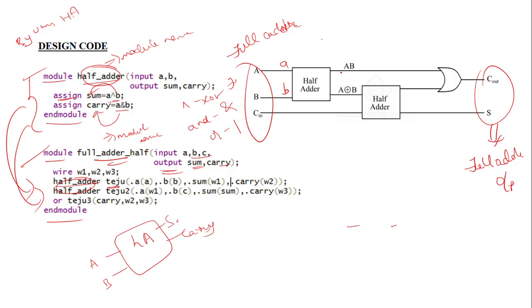For the second half adder, what you have to write here is simply a connection. A connection is nothing but connecting two ports, and we represent it as a wire. We can take any variable, which simply carries this output to this input port. For carrying from one point to another without any storing of values, we use the wire data type. You can use any name, so that's why here I represented them with wires W1, W2, W3 like that.